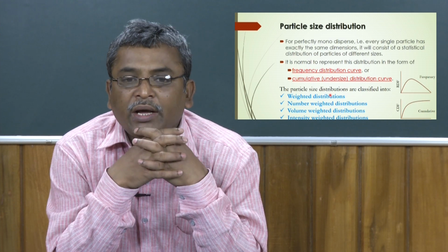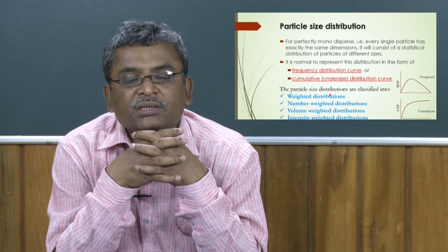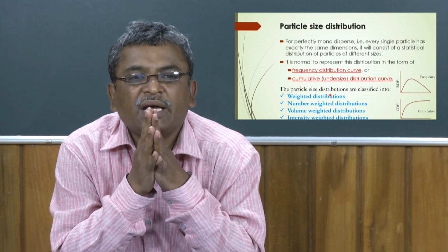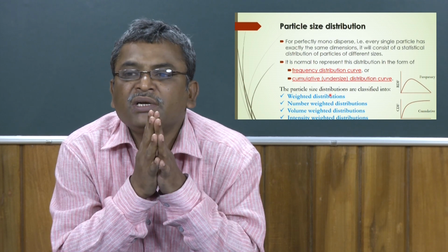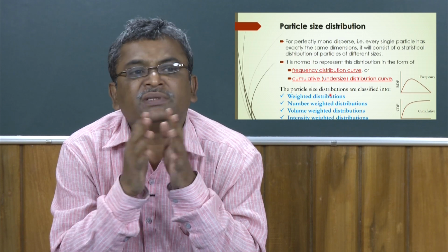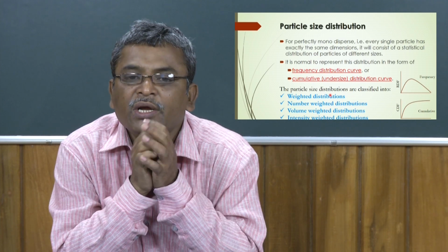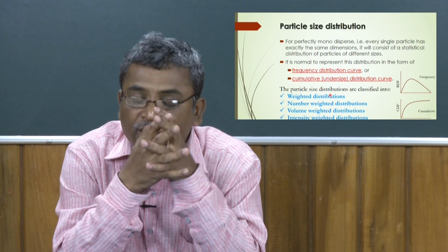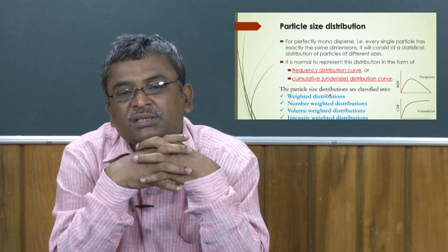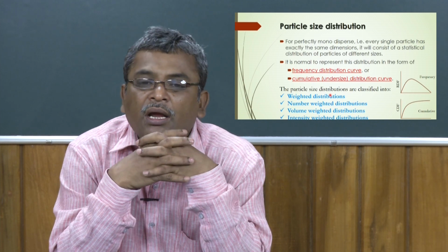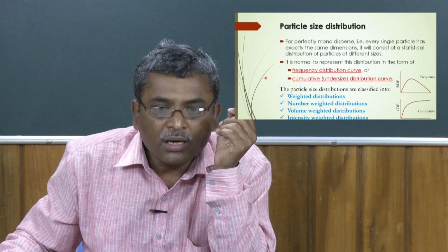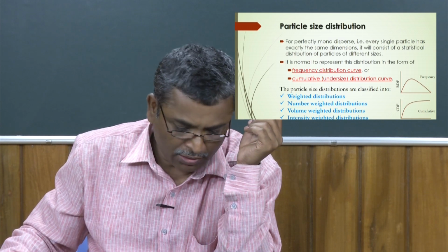more. Whereas, if you use larger or medium sized particles, you will see some heat transfer operations, mass transfer operations, even some drying operations will be more favorable. So, you have to know what the particle size distribution should be. Okay. So, this is important for the fluidization operation.